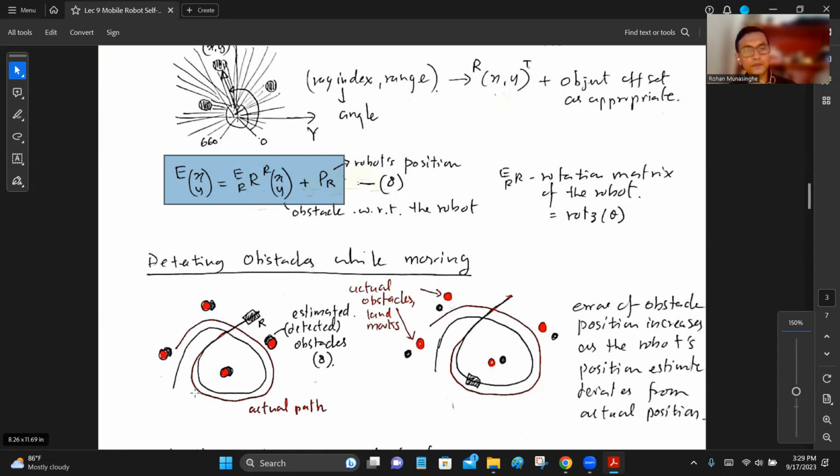So what will happen? Here you can see the red dots are the actual obstacles. Say 4 trees in that area. You do this testing, 4 trees, the red ones. You know the positions of these trees, but the robot doesn't know. When the robot moves in, it gets the LiDAR map, calculates the position of the trees, transforms them to the world coordinate frame and plots them using these black dots. Now you can see the black dots and red dots are not coincident. There is an error.